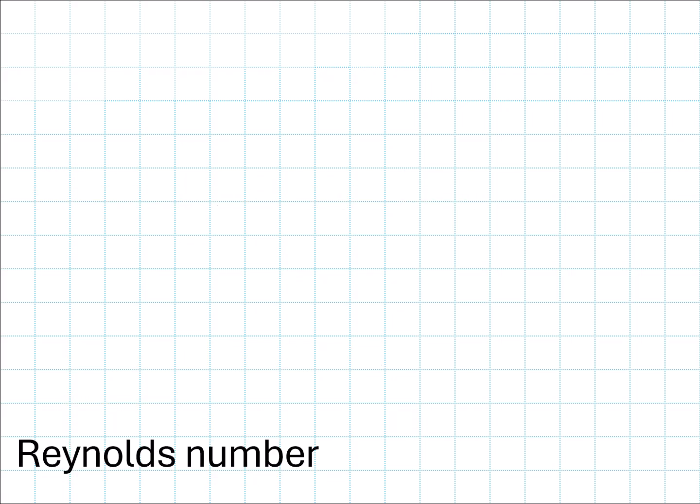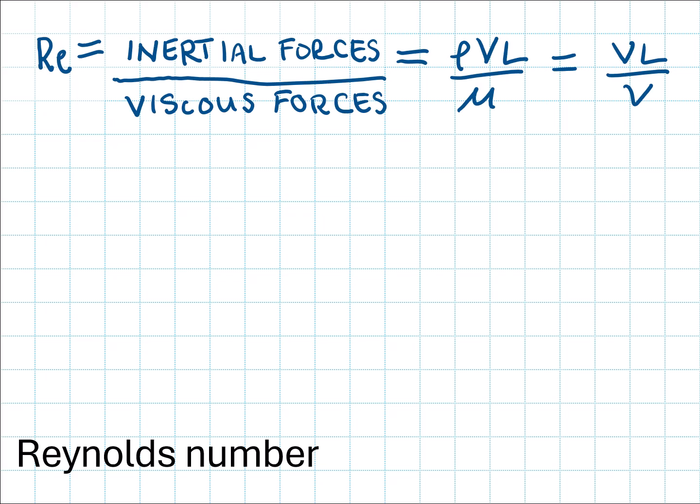We've calculated many a Reynolds number by this time in the course, so of course we understand now that Reynolds number is a dimensionless parameter that expresses the ratio of inertial and viscous forces within fluid flows and is governed by these equations, where our parameter rho is the fluid's density, velocity is the velocity of flow, L is a length scale that's characteristic of our problem's geometry, and mu and nu, respectively, are the dynamic and kinematic viscosities of the fluid.